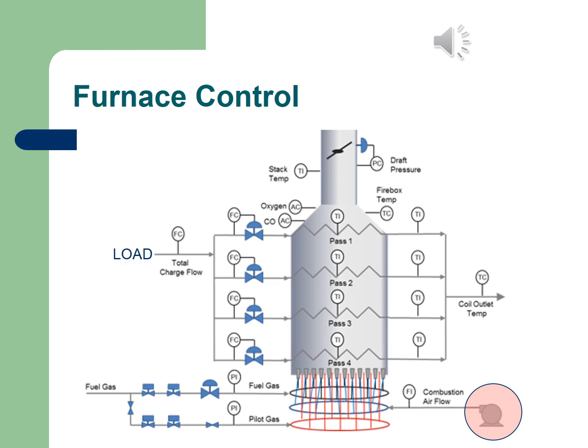Another very important aspect associated with the fuel, of course, is your airflow. You can see that the flow of that specific air is measured by a sensor, and that can be adjusted. There's no feedback loop indicated here, but you can think that eventually you will control the blower that blows the amount of air containing the oxygen that's needed for this combustion.